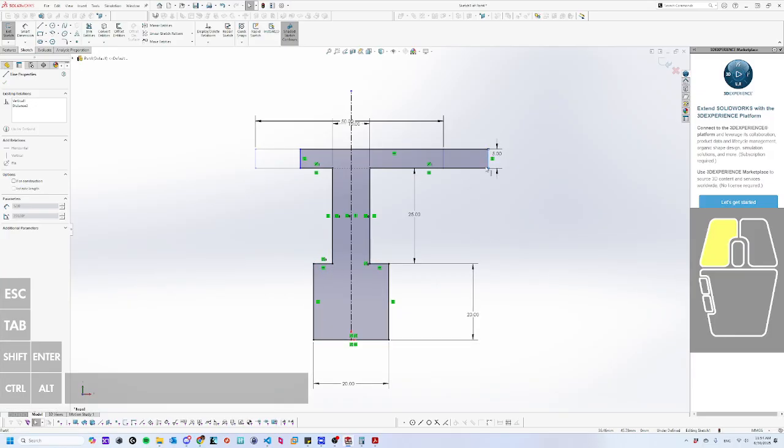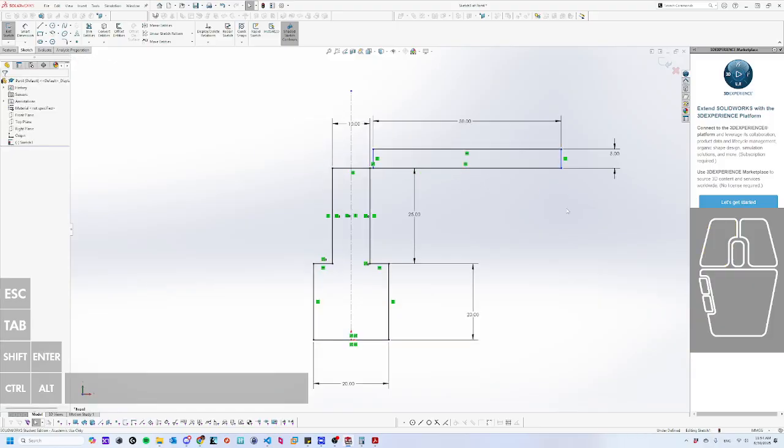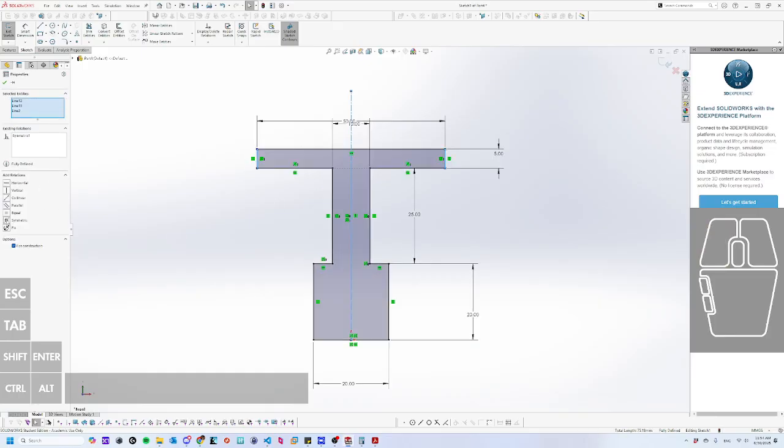So only 2 lines left, and it's the same problem. This might be a good time to show. Let's see what happens if I do this. Oh, it fixes it. Okay, so I guess SolidWorks knows that it wants the 2 solid lines around the dashed line. So selecting the 2 again, and then selecting this has centered the 2 lines around the object. I can see down here on the bottom right that my object is fully defined, and so this part is complete.